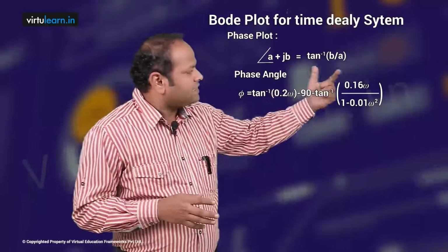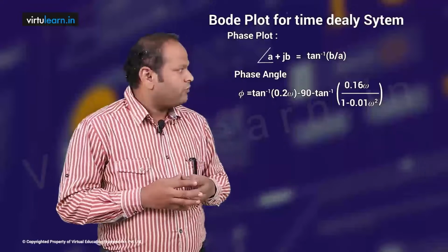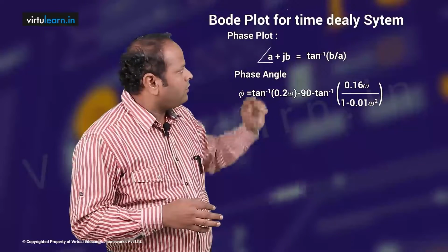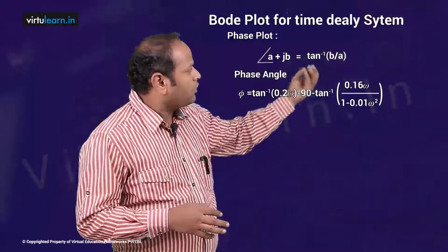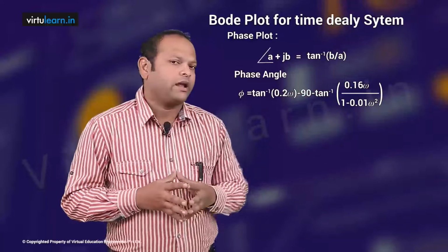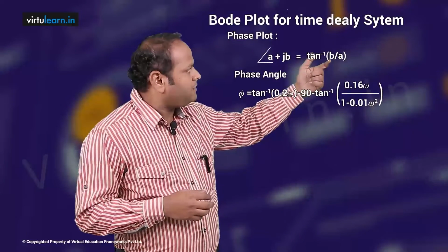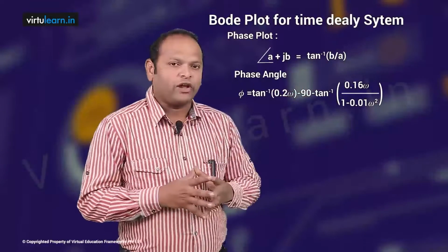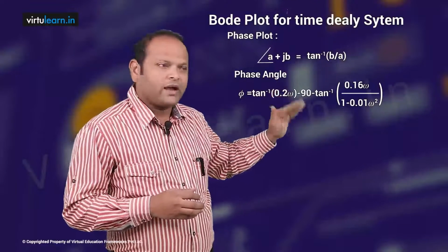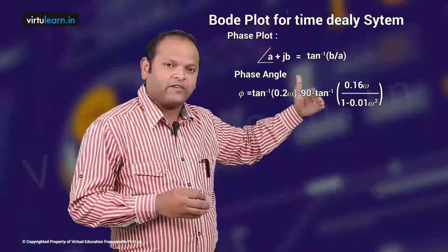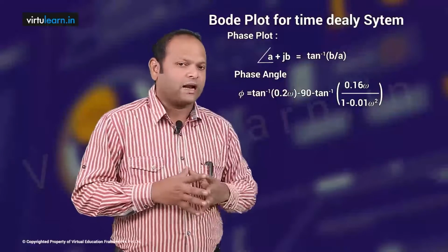But this phase angle expression is valid only for a certain range of frequencies. So when you prepare a table of omega versus phase angle, we need to look at this particular term and take care about it. We can simply approximate this particular term like this, one way of approximation. So what is omega n? Omega n is omega C2, that is 10 radian per second. Before that we will use one formula, after that we will use another formula.